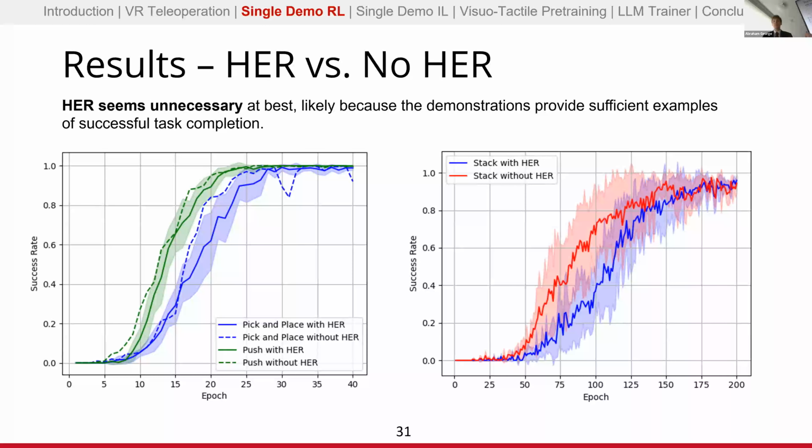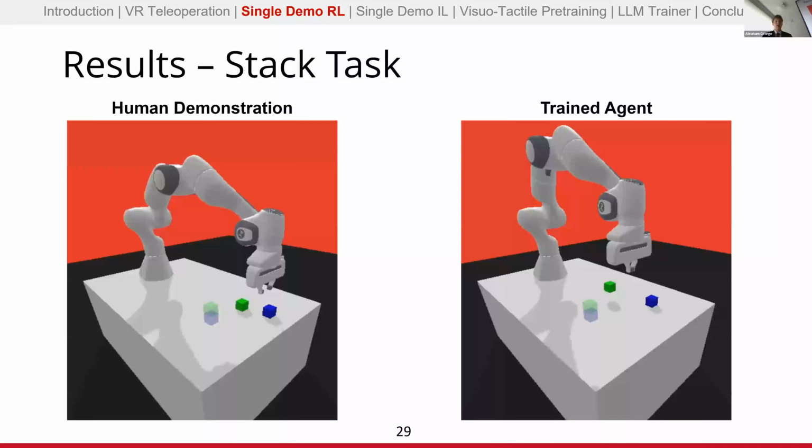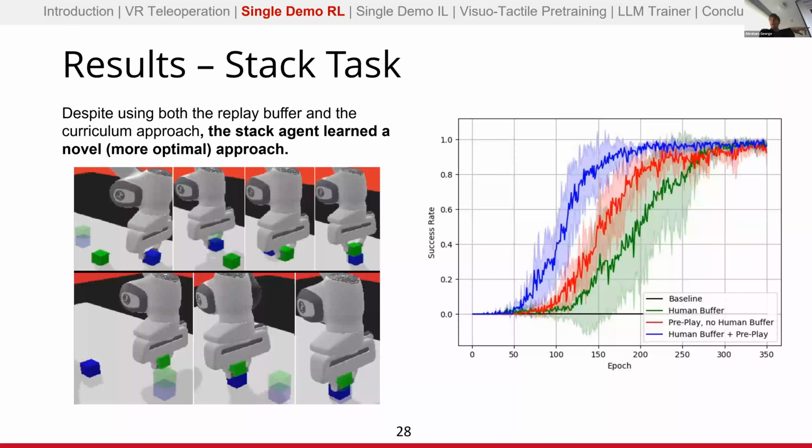So that means that if we don't need HER, and specifically the reason why we don't need HER is because HER is used to generate these successful demonstrations, we can instead use our already existing successful demonstrations, where we don't need to broaden the definition to any two locations in the scene for the goal blocks. We only have to train them for them stacked. And I think that's very relevant to this idea of training a different policy, because whenever I'm training HER on this, if the end location is separated, it has to use this top policy to do HER. It can't use the bottom policy for stacking them and sliding them.